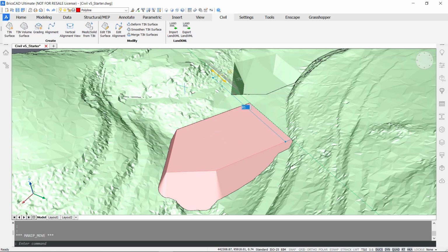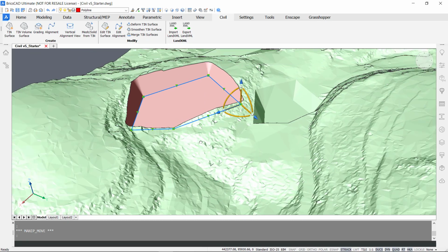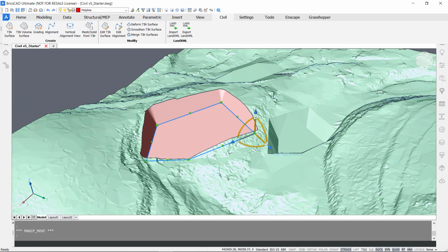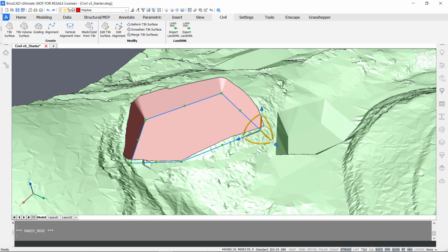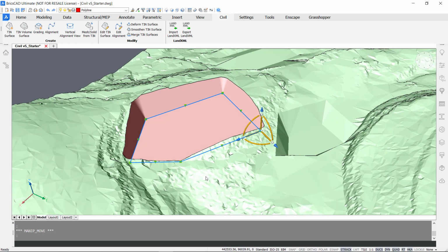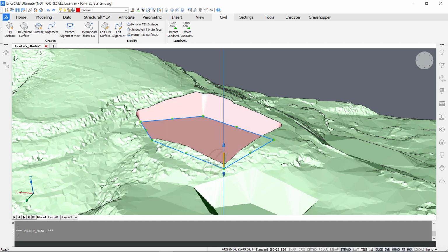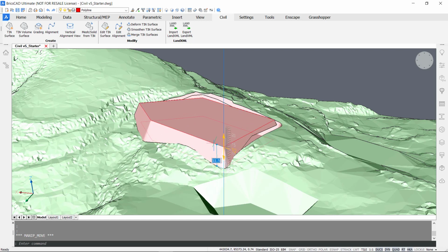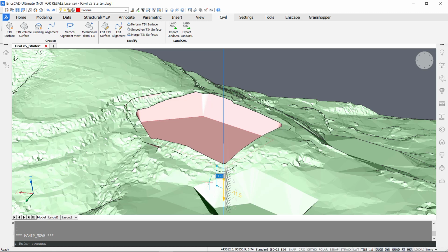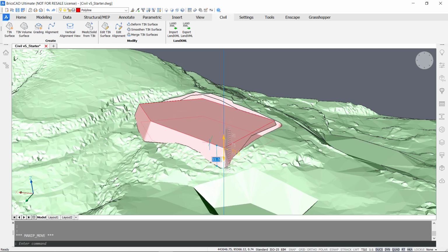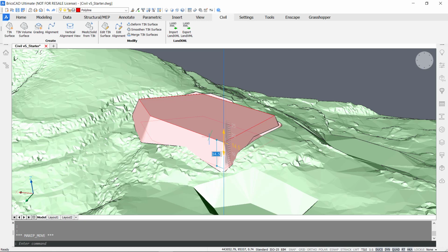So let's say I move it here. You will see, instead of a slope that is a building path as in fill volume, according to the existing thin surface, you will see that's actually cut out parts of the same slope degree. So it's a little bit different, but it adapts immediately depending on what height you set your new entity to.